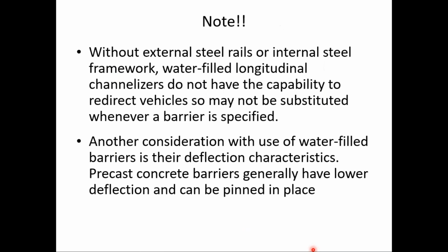And I did want to point out too that without external steel rails or internal steel framework, the water-filled longitudinal channelizers that I know are popular in many places don't have the capability to redirect vehicles, so they may not be substituted whenever a barrier is specified. Another consideration with the use of water-filled barriers is their deflection characteristics. Usually if struck, they will move a significantly greater distance than the precast concrete barriers that have smaller deflection, and actually you can pin those into place.